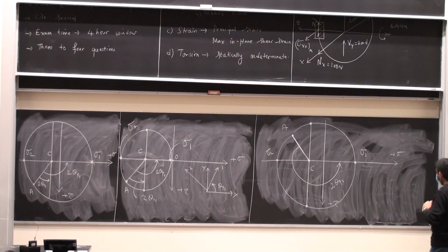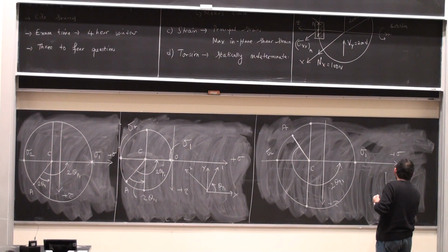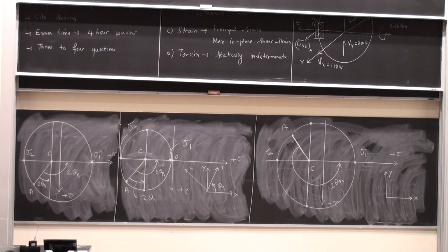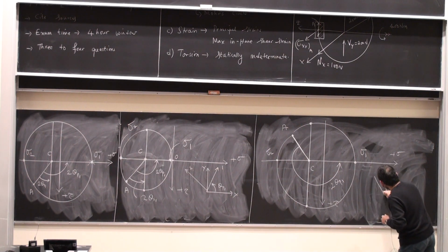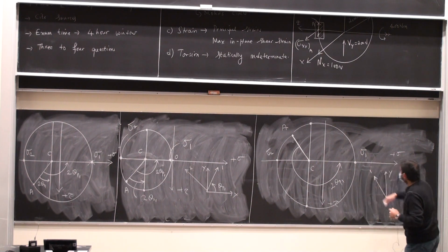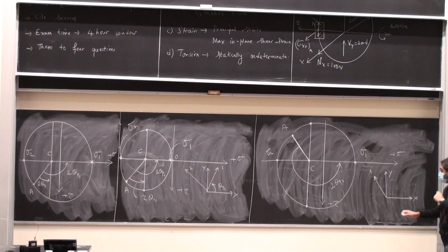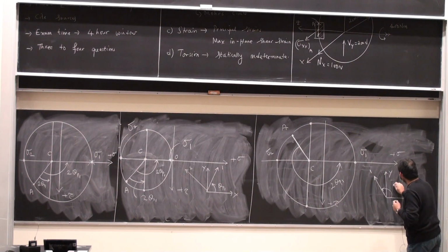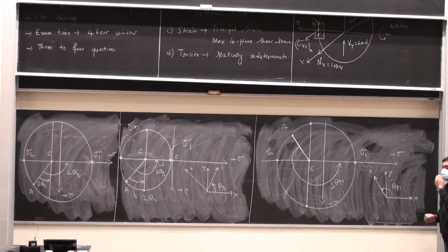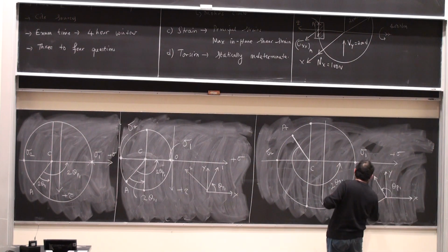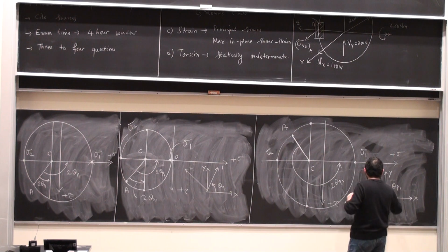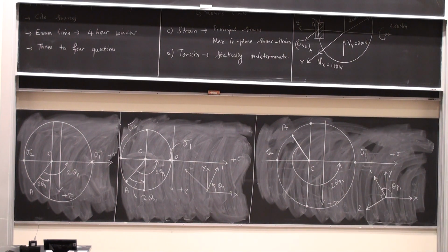So, if I now draw out x and then y, theta P1 in this case is going to give me the location of the 1 direction, which means that the 2 direction is going to be perpendicular to that and coming out this way. So the orientation of the principal plane itself is given to me.